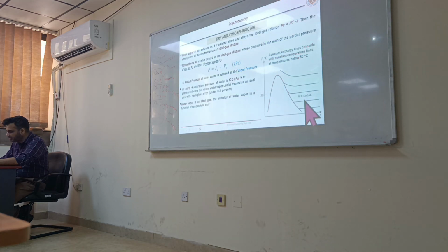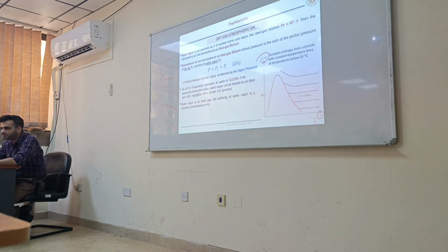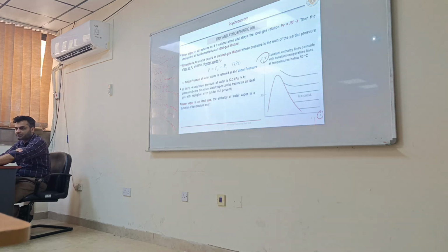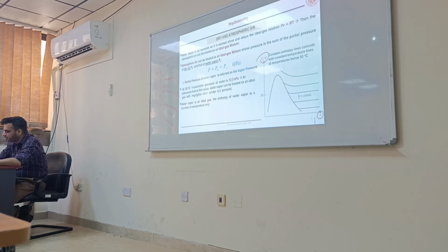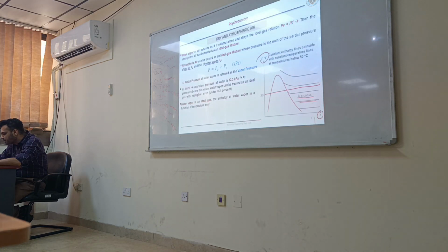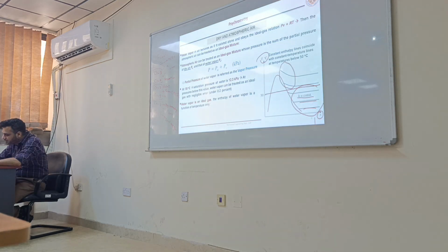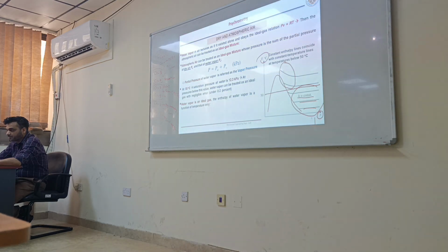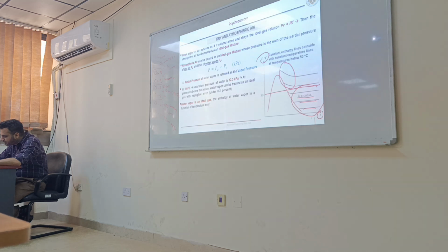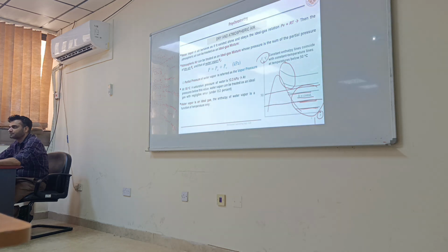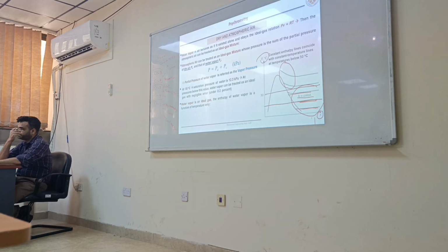If we show enthalpy lines on this TS diagram, which we normally do not show, they look like this. When you are below 50, enthalpy lines are just horizontal in the gaseous region. Above 50, they are a function of pressure also. But below 50, they are only a function of temperature. For one particular temperature, enthalpy is constant for water.